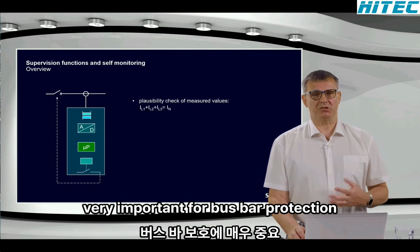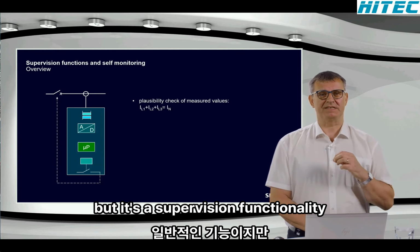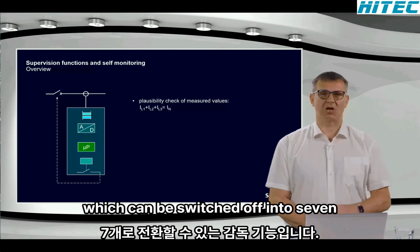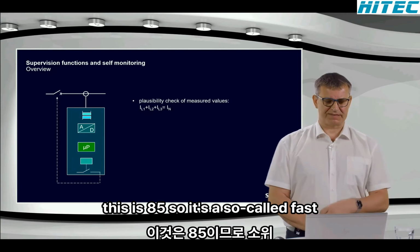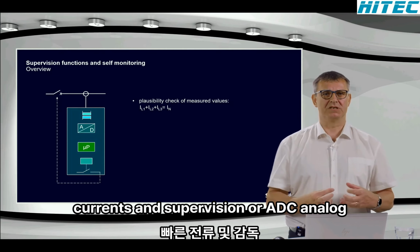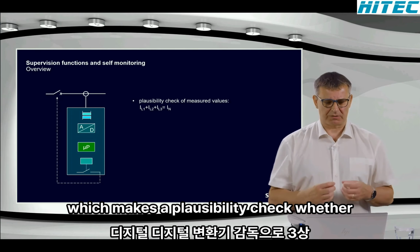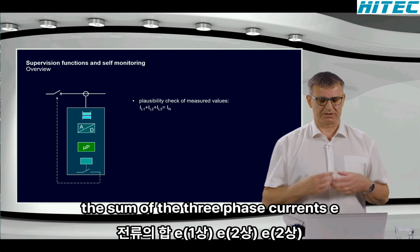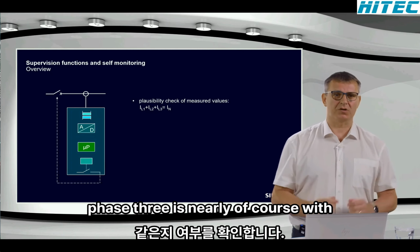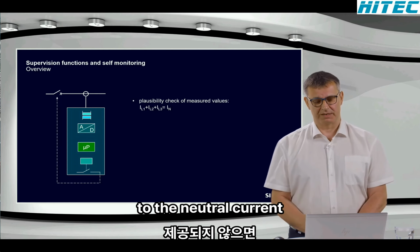Very important for busbar protection. It's a general feature for SIPROTEC 5, but it's a supervision functionality which can be switched off in the 7SS85. That's the so-called fast current sum supervision, or ADC, analog digital converter supervision, which makes a plausibility check whether the sum of the three phase currents, IL1, IL2, IL3, is nearly, of course, with some uncertainty, equal to the neutral current.